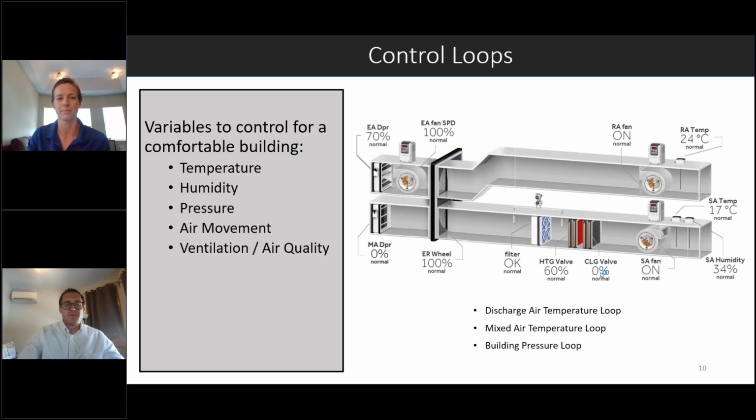Having a modular controller in place that allows for spare capacity is very good for something like an air handler. A lot of times with an air handler, you're probably going to want your controls contractor to provide the controller themselves rather than a factory packaged control, unless you really know what's going on there out of the factory.